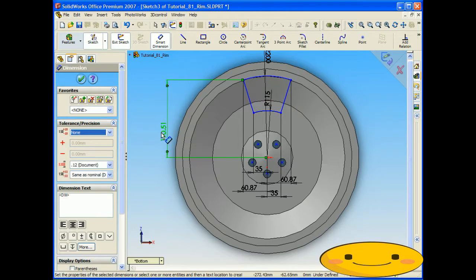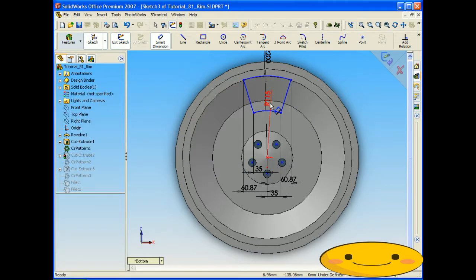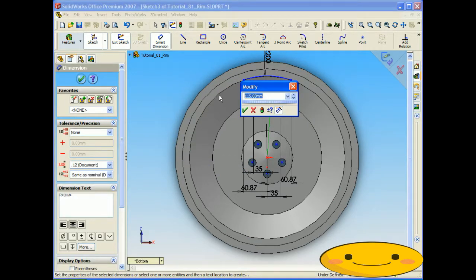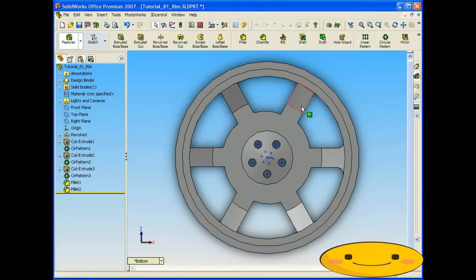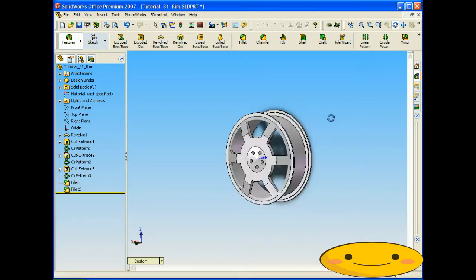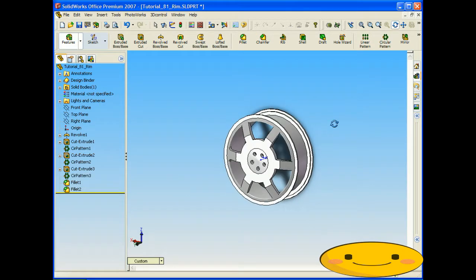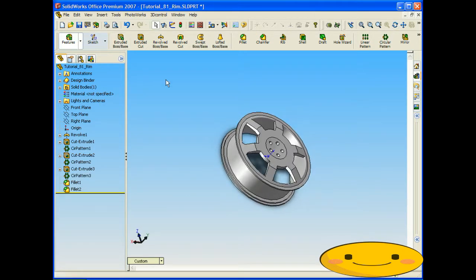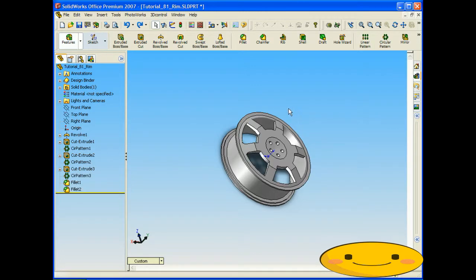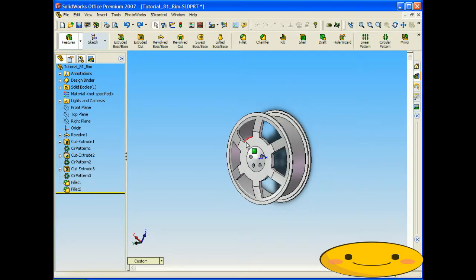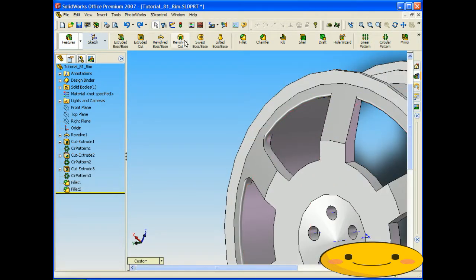And once it's over defined, delete that. So let's make this radius here, let's make it 100. Click OK. Click accept. And now we just pulled it in a little bit. So you can play around with those and you can just edit it. Now, let's go back to how it was before. And let's just finish doing these fillets all the way around.